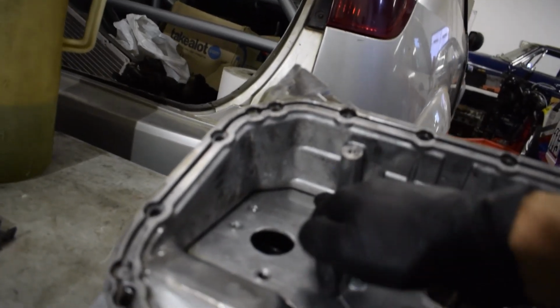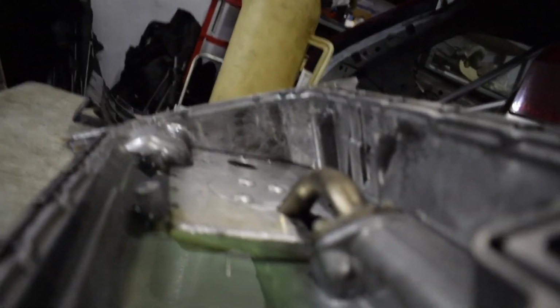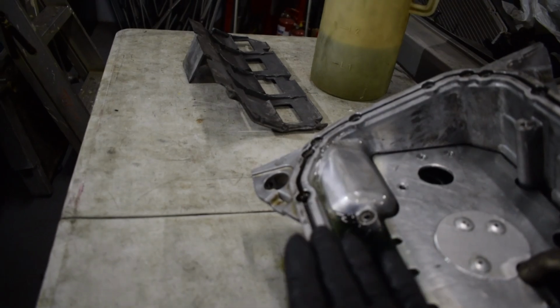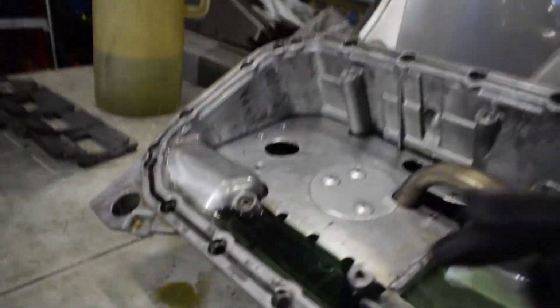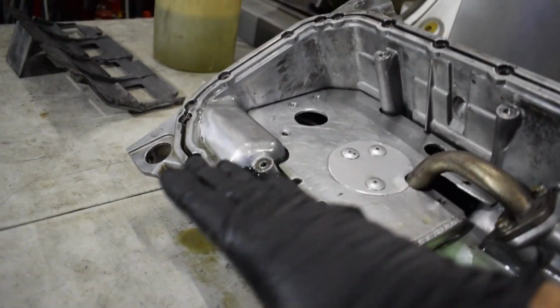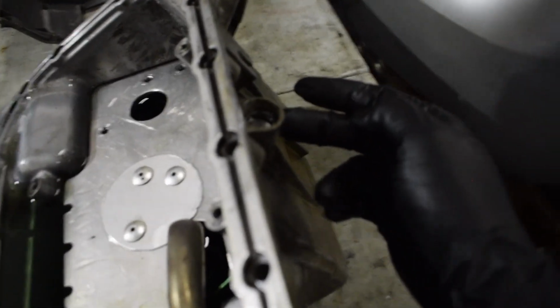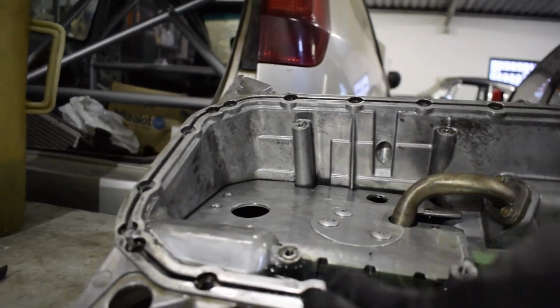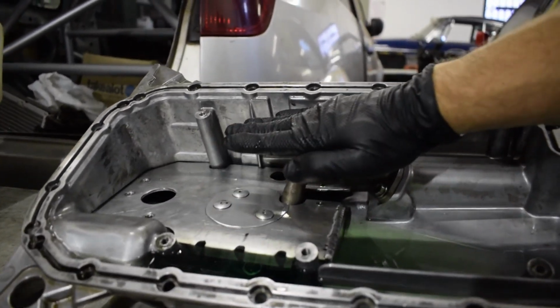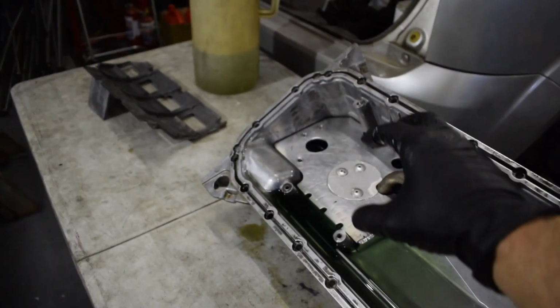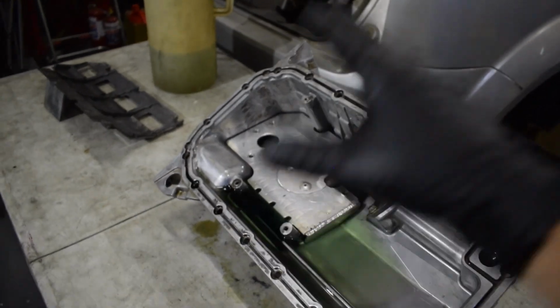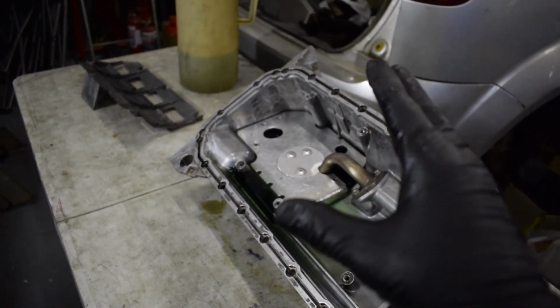So that is basically what's causing it, as well as the oil sitting super high up in the block. I think the oil line is probably, well, here we can see that it's already higher. We've still got another 1.5 liters to go there. So the oil level is sitting up here, more or less, probably 50 mils above, or maybe 30 mils above here. So it could be even in line with this line. It's probably just below your dipstick line, which if you draw a straight line is about 30 mils above the deck here. So that's where the oil level is naturally. That means this sump doesn't have enough volume in terms of the design for a race situation.